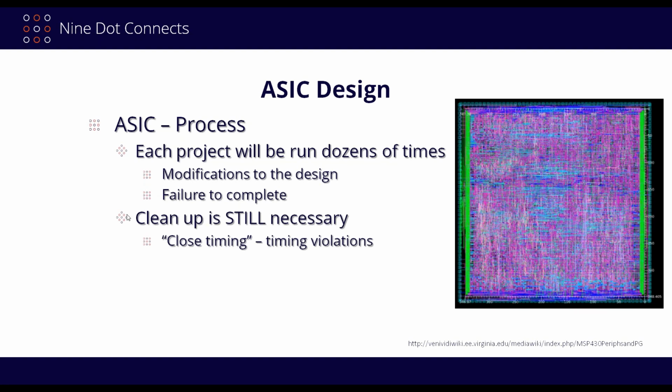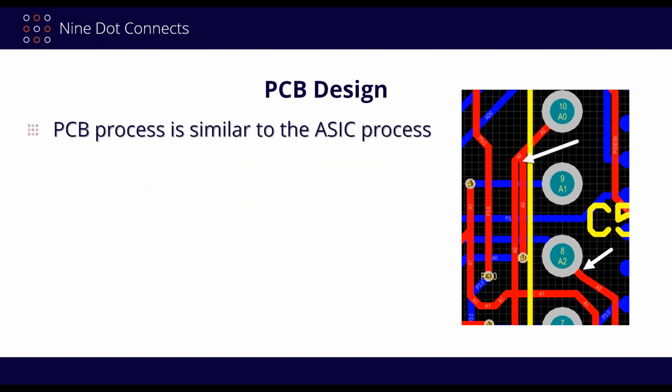And lastly, and this is what's most interesting, these tools are $100,000 tools. And it's a very, very competitive industry. There's a lot of money in this. And what's interesting to me is that even if you run this thing dozens of times, and you've got your scripts all nice and set up, and you finally got it down to where it seems like it's going to work, you still will have to go in and close the timing violations. So no router, even though it's $100,000, and even though it's state-of-the-art and the best one out there, does it perfectly. So if they can't even get this thing to run perfectly, we have an unrealistic expectation that we can get a PCB router to run perfectly as well.